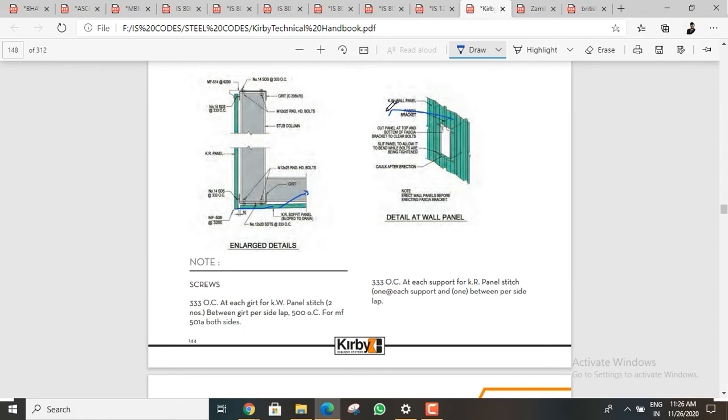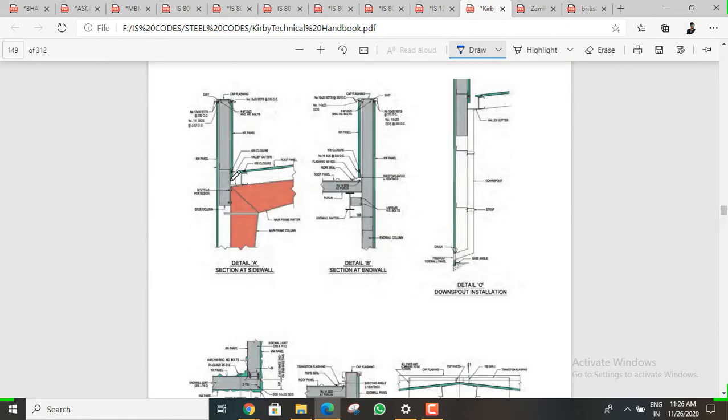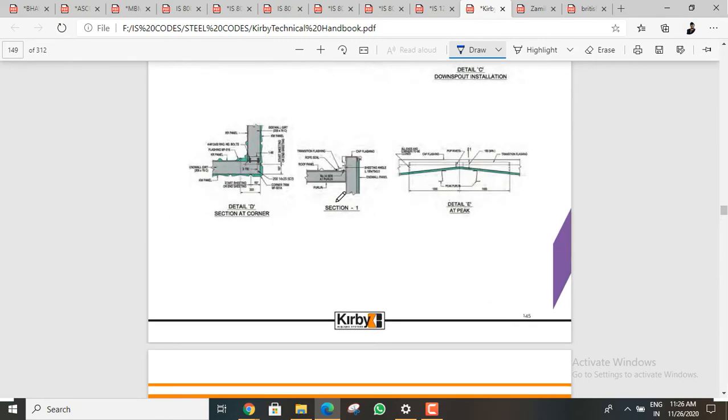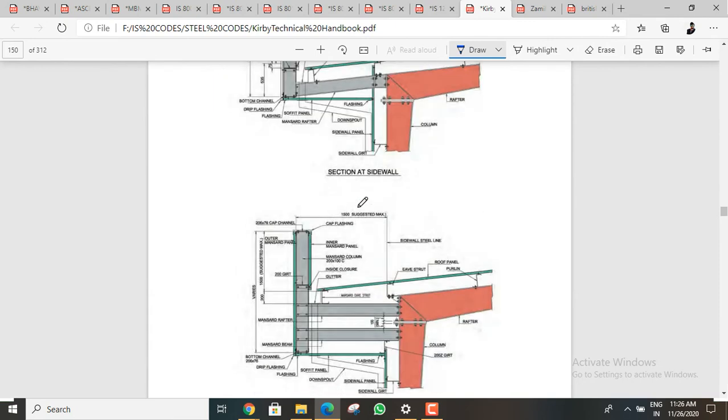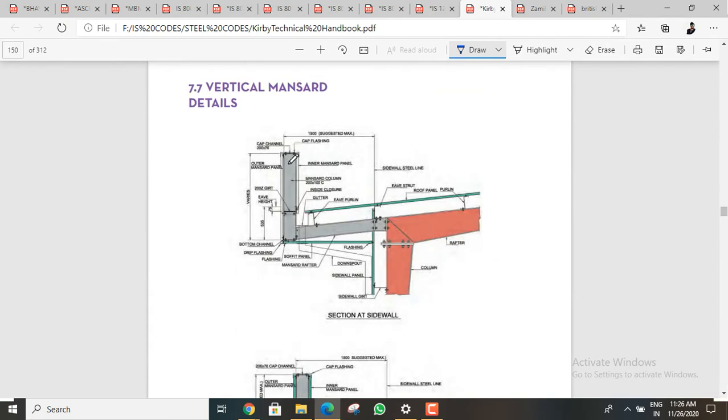Okay, and this is a sheeting, and this is also sheet type, this one. Okay, C type purlin, and this one is exactly seating, and this will be purlin. So if it is on the top, we call it a purlin. If you place it on the side, it is called a girt. Okay, girt. Yeah, so let's come to here. This will be the somewhat vertical fascia.